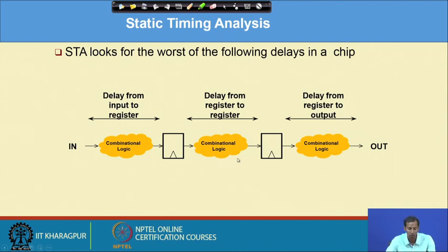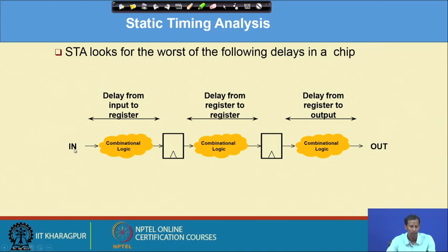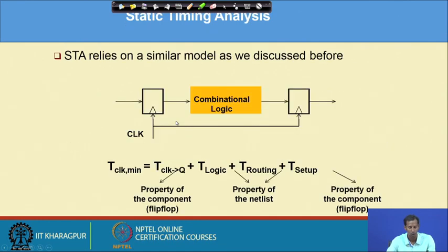Okay. So now we have to calculate the timing analysis for this. STA, how can we calculate? Whenever there are inputs to the registers, then register to register, then register to the output. Here you see inside this register to register, whatever the logic is, will be considered as the minimum timing requirement for the corresponding clock.